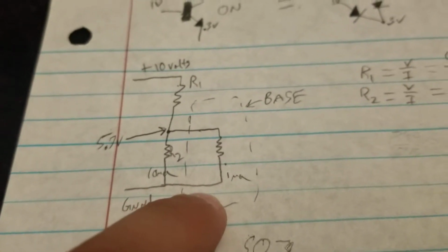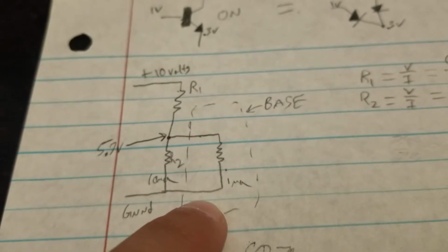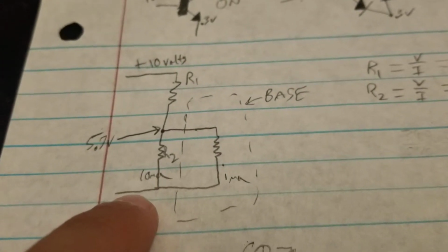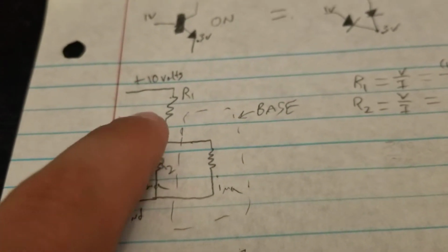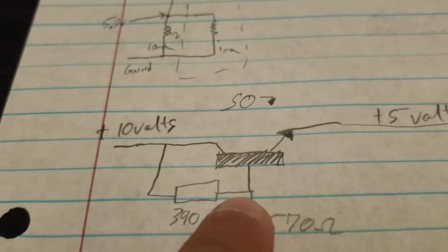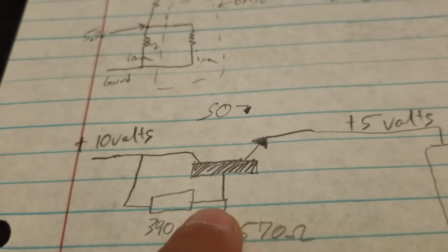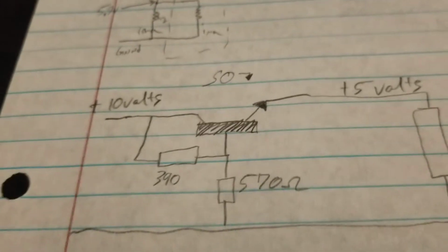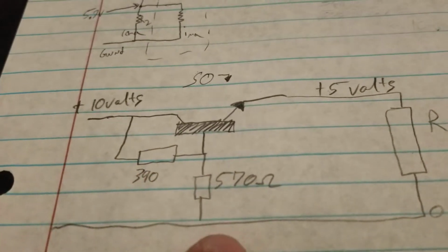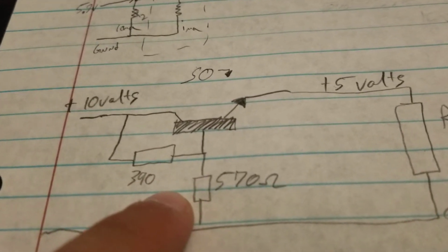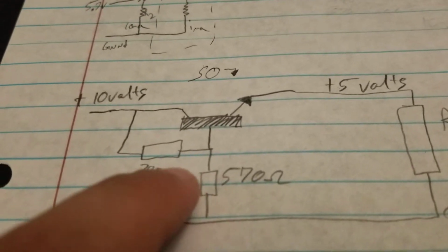If it's a light bulb, as it heats up, the resistance changes, which changes the current. And these resistors would have to be a fairly substantial value. However, down here in this transistor, we could just put a big beefy power transistor and call it done. And so, meanwhile, only milliamps are flowing down here to give us a pretty stable voltage,